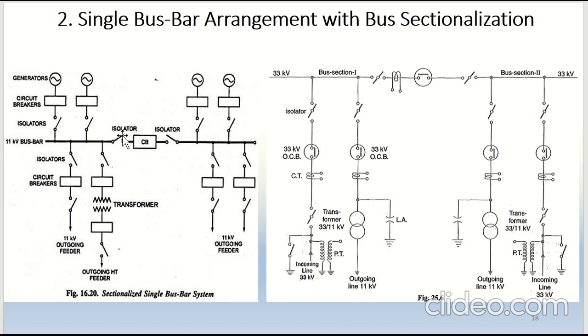is an isolator. So if you want to work on the right hand side, then I just have to open the isolator and the circuit breaker of this side, and this entire thing is de-energized. The right hand side is de-energized for me. My loads on the left hand side can still be operating in that case.